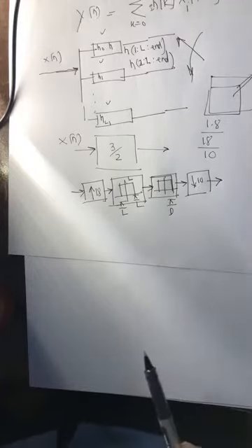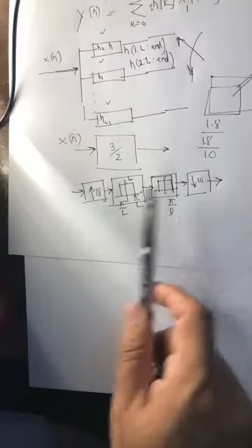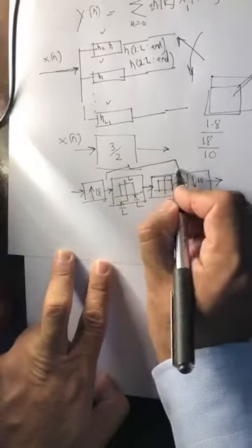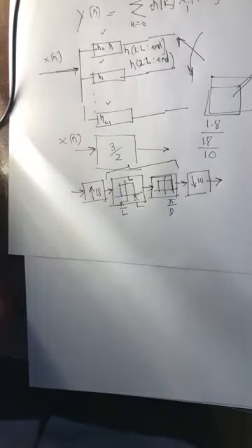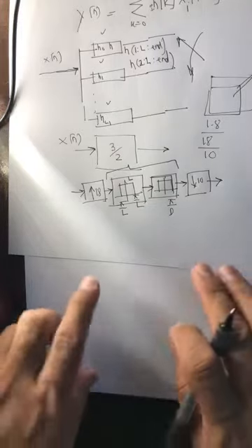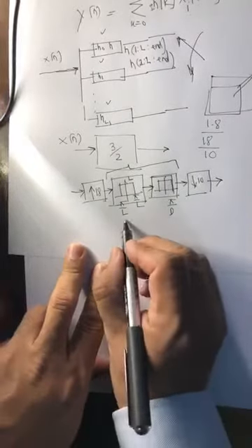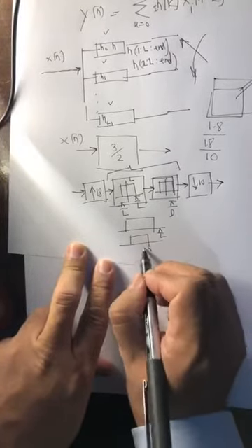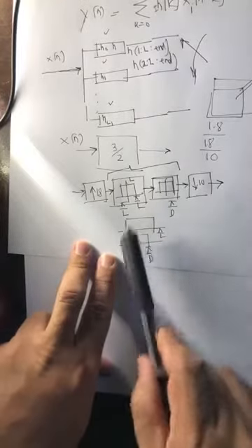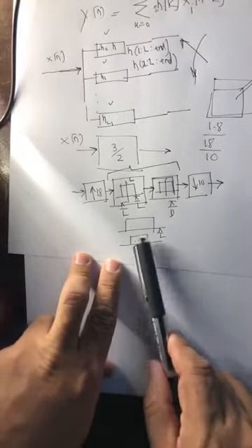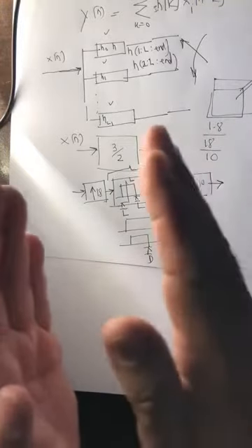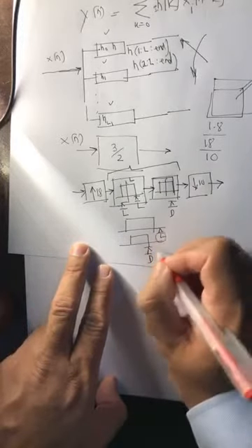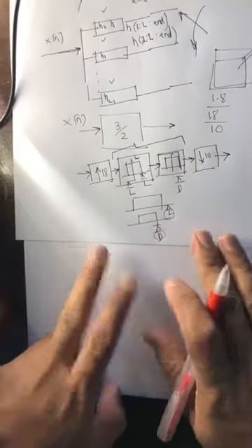But obviously sometimes you may argue that putting two filters in cascade does not make any sense, because they multiply in the frequency domain. Why not make one filter out of them? Yes, you can make one filter out of them. And how you do that is by finding out, for example, this is pi over L and this is pi over D. Once you multiply them together, you will be left with only pi over D. So find out which one is smaller, and you pick that. So whether L is larger or D is larger, you select one filter.